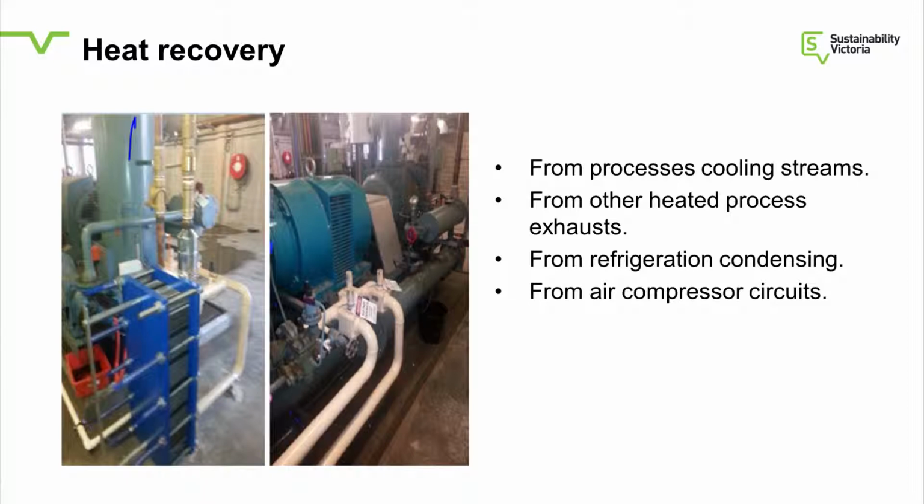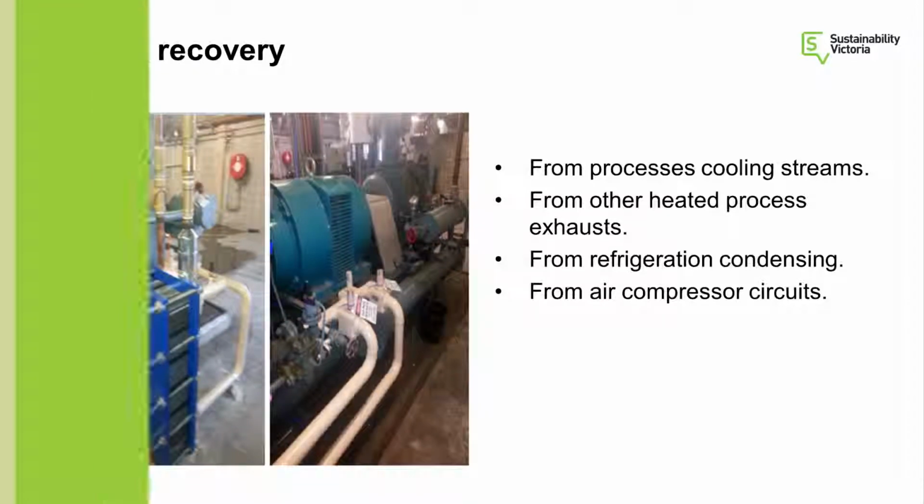So that does two things. It reduces the energy for cooling on the refrigeration plant, but it also replaces the gas for preheating the water before it goes to the gas system. So they work really well. They're reasonably capital intensive, but I think the way energy prices are going, more and more people will start to recover heat from those systems.